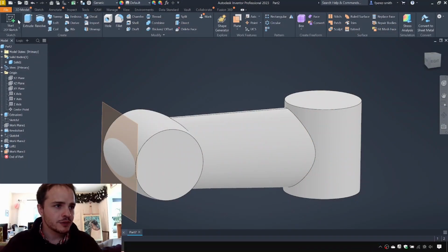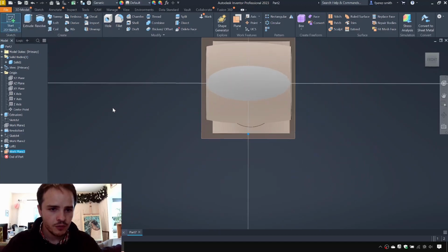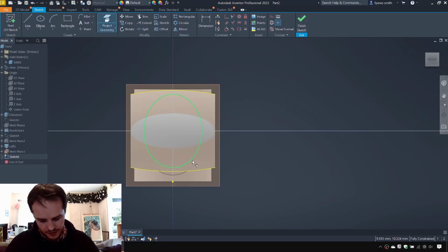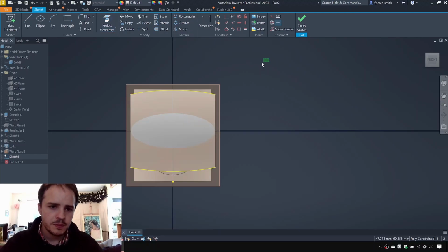Just to refresh your visuals, what we've got here, the bolts come through, they're centrally aligned. And so we're going to model it at the front, and then we're going to make it so that it extrudes backwards. So we'll start off by coming to 2D sketch, making a sketch on the work plane, and we'll come along here and say project geometry, and we'll grab the upper curves of the barrel. And now we'll take a quick measurement and we'll see, yep, it's about 13.5 millimeters OD. So we'll make those projected lines construction. Good practice. I keep on doing this and I think I go too fast. I'm sorry if I do.